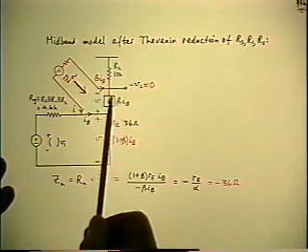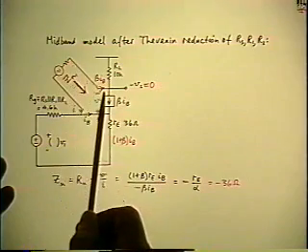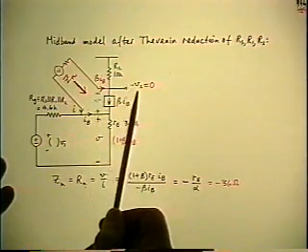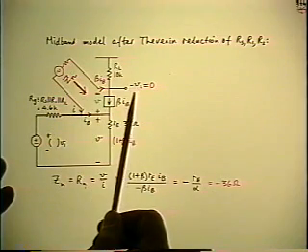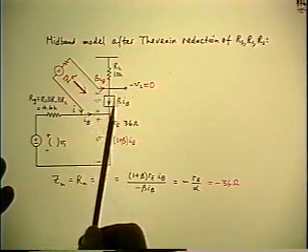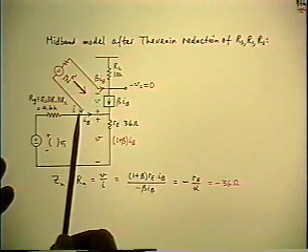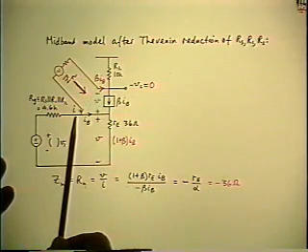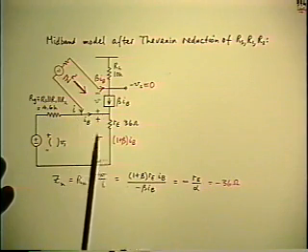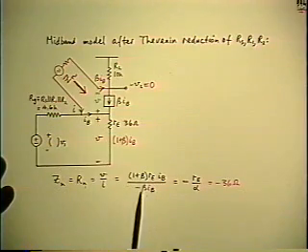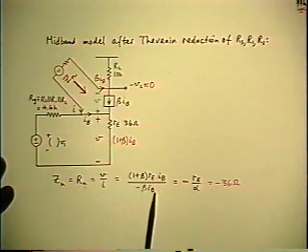What it does say is that the collector current is equal to the current to the second source, because there's no current in RL because of the null. So the current in the second source is equal to beta IB, but that current I've already defined as minus I. So in the denominator, V over I that I'm trying to calculate, the denominator I I've replaced by minus beta IB.